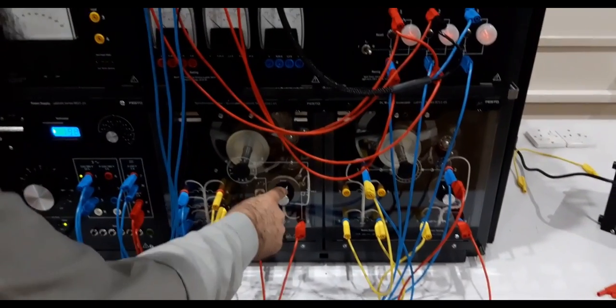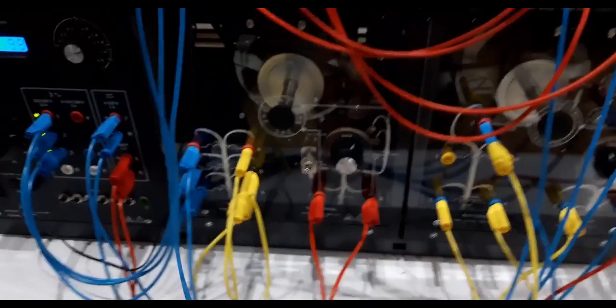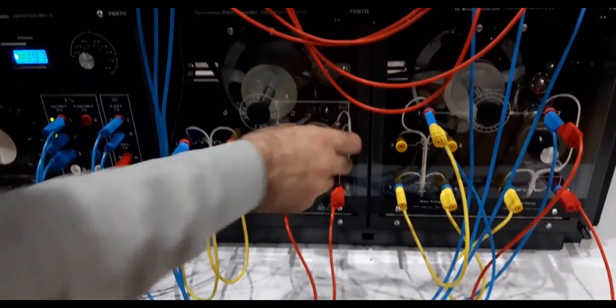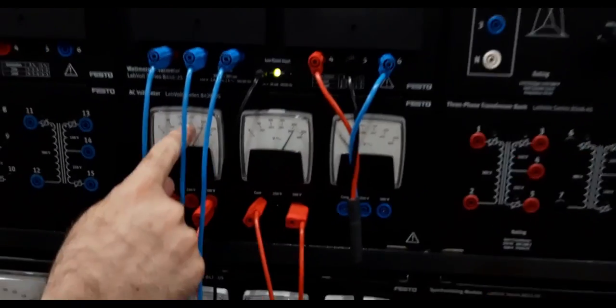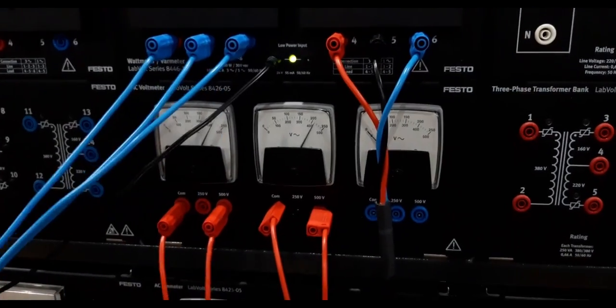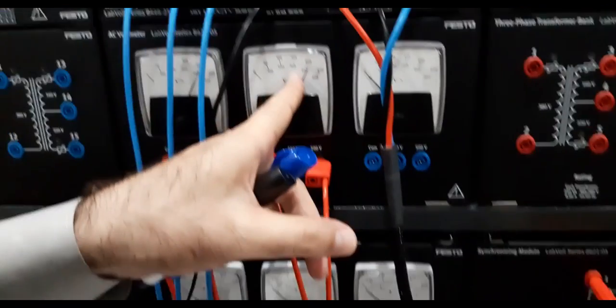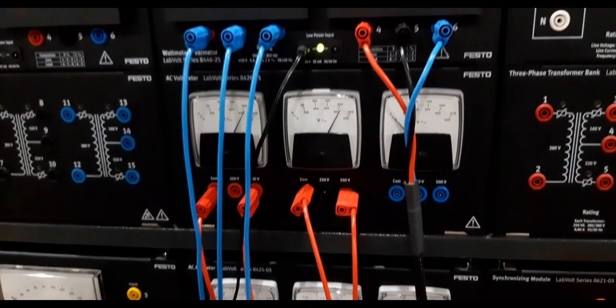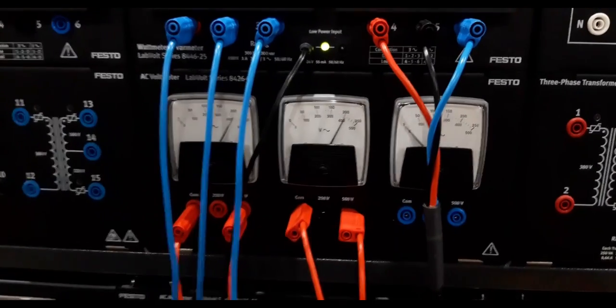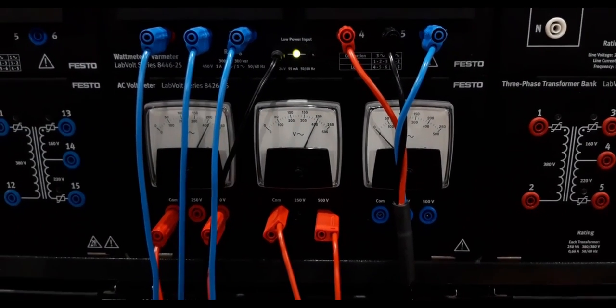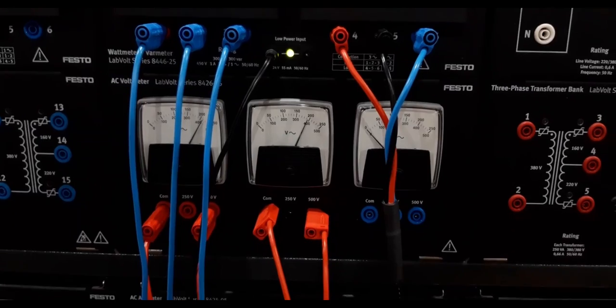Now let's say this is the field, this is the main field of the synchronous generator. So now if I change the knob of the exciter, if you look here, the voltage of the WAPDA and that of the system is more or less the same. So now if I change the excitation, you will see this voltage will vary because I have not yet connected it to the system. So if I change the excitation, you see, this voltage is fixed because it is WAPDA. This varies.